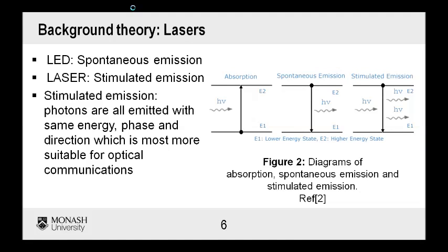Lasers are what's used to transmit light for an optical fiber, as opposed to LEDs. The reason why is LEDs use what's called spontaneous emission, where photons are excited up to higher energy levels, and at this point, after some period of time, they'll drop down and release a photon.